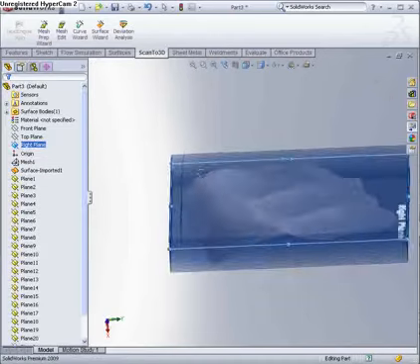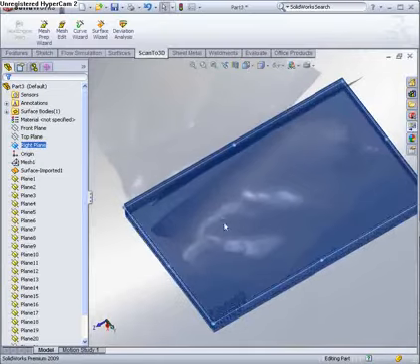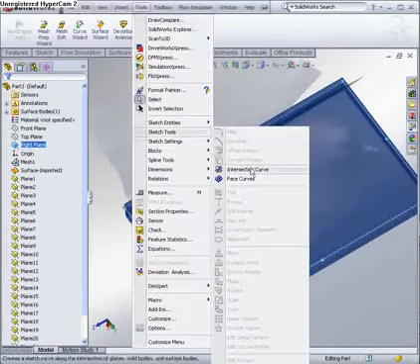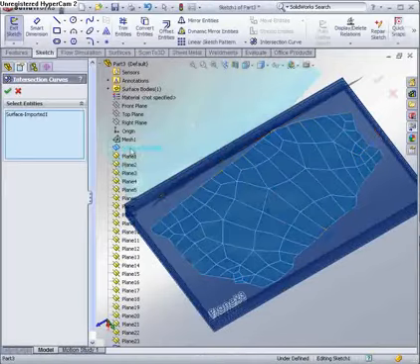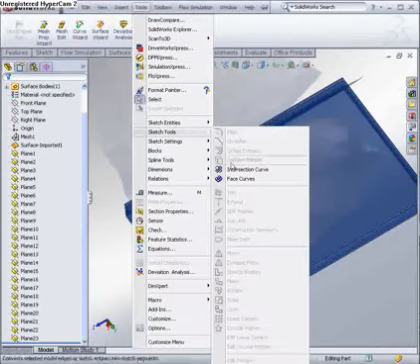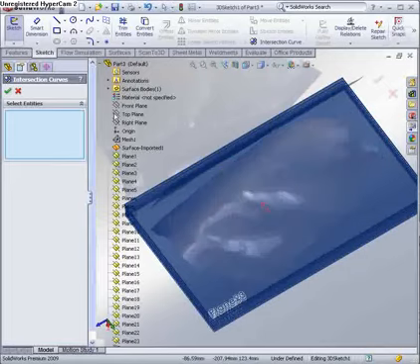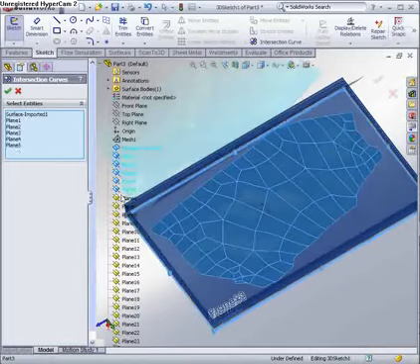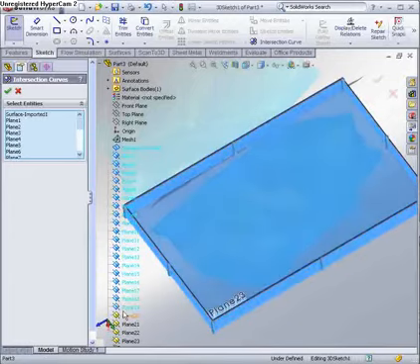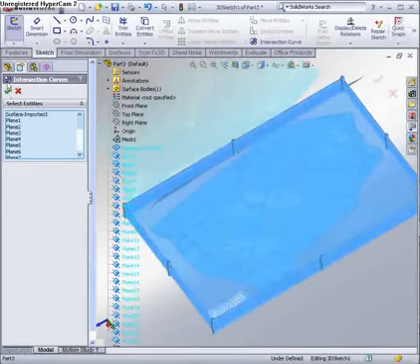We're going to make a contour, so we're going to use the sketch tool, intersection curves, and from that I'm going to select the surface and, hold on, let me exit my sketch before I do that. Intersection curves. I'm going to select all of those planes. Okay, and that will process and we'll get a single 3D sketch that contains a number of 2D planes with the contour information in there.